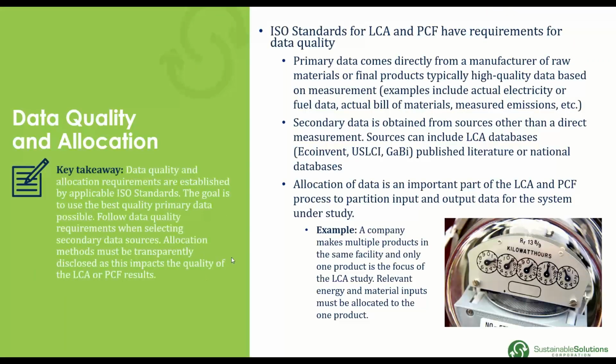I do want to take 2 minutes here and talk about data quality. This is really important. The quality of the LCA is going to be dictated by the data that we utilize. And we look at two types of data. Primary data is going to be data that we get directly from a manufacturing operation. That would be measured data. Typically, we can get meter data on electricity or natural gas use, or we're going to get an actual bill of material with real weights or mass percent, or we're going to have measured emissions coming out of that factory or operation. And then the other source of data would be secondary data.